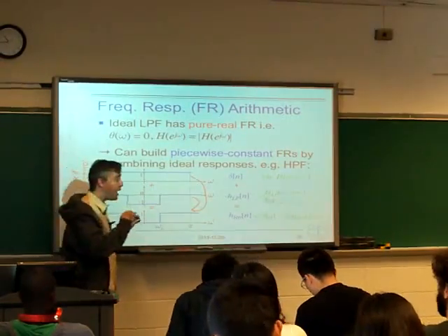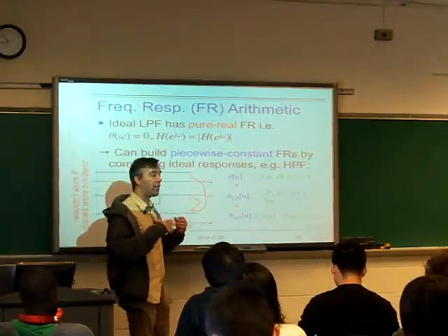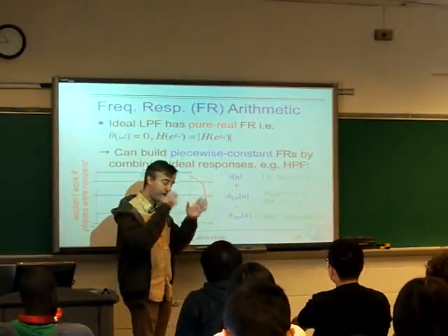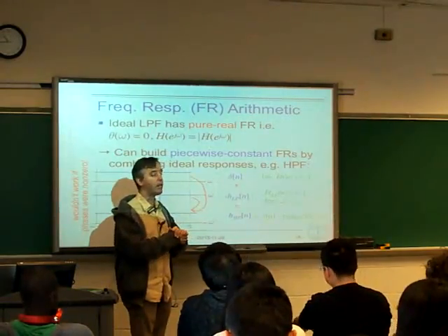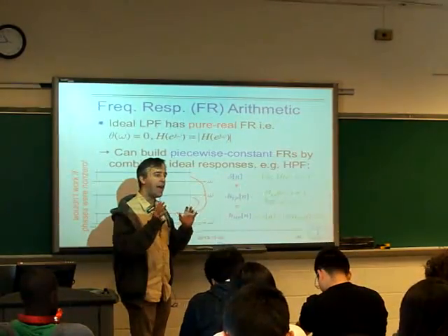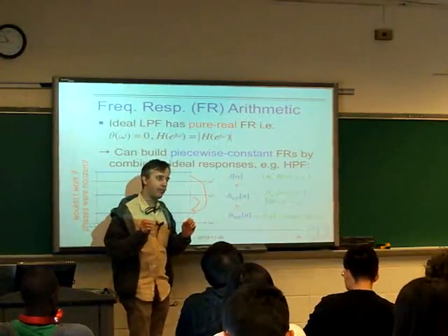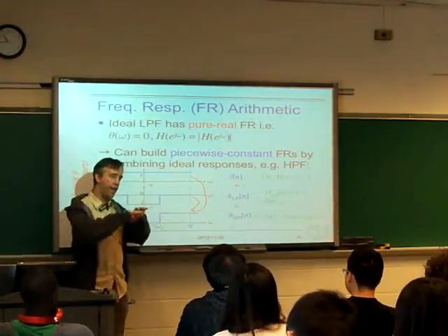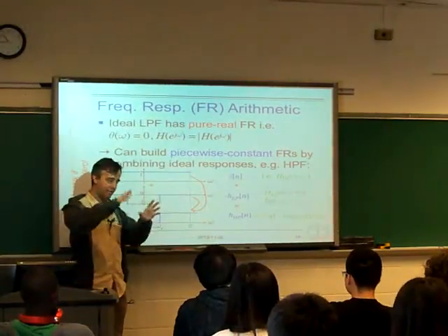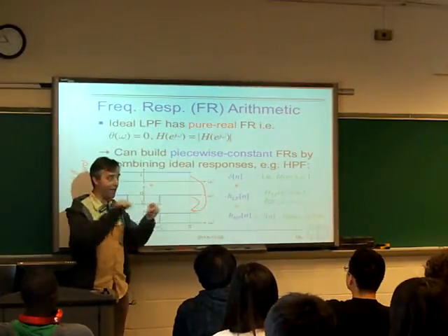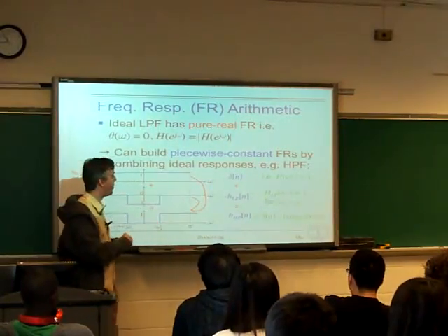Okay, so with these effectively zero phase filters, if the filter is really centered on 0, we have a magnitude response which is pure real. If the phase is 0, the complex number is always on the real axis, so it's always a real valued thing.